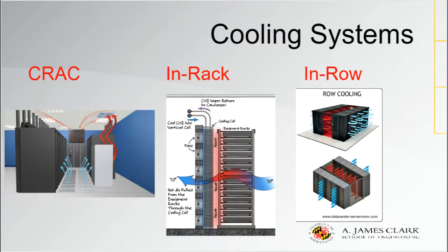In-rack cooling, meanwhile, is basically a bunch of CRAC units dedicated to a certain rack, directly mounted within the IT equipment. The airflow paths are much shorter, therefore it reduces the fan power required and increases efficiency. All of the rated capacity can be utilized and the highest power density can be achieved, and it's targeted to the actual needs of the specific racks, serving different power densities and purposes.